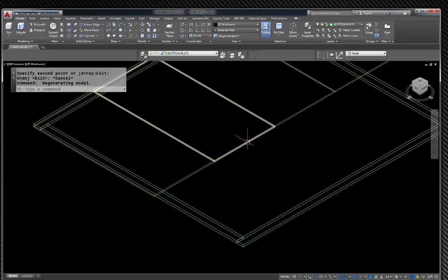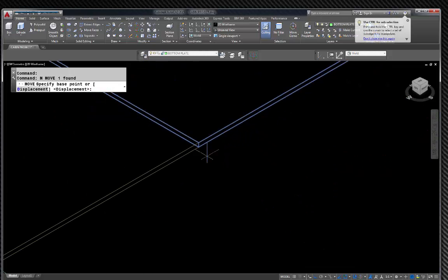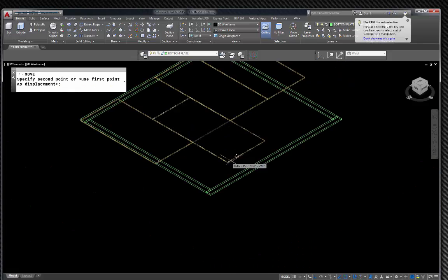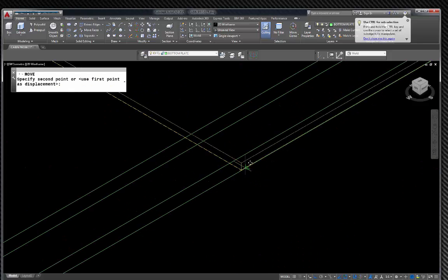Now here's one of the things, you can just go ahead and lay yours out. I'm going to do the way that we want to do, which is we want to offset plywood so you don't have a running seam when you're in your flooring. So what I'm going to do is I'm going to move this one from this point here all the way over to that.